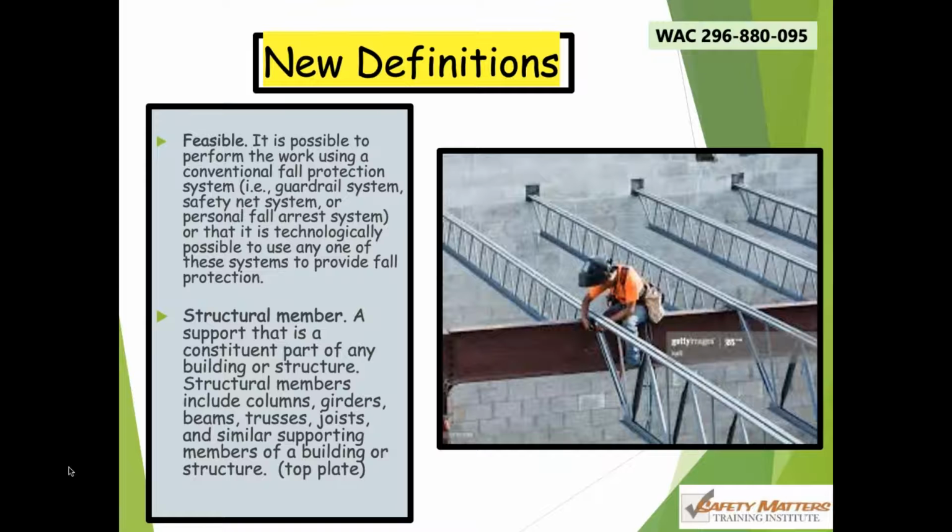So we're down to 2 trigger heights, you guys. We have 0 and 4 feet basically are the 2 trigger heights. OSHA has trigger heights of 0 and 6 feet, and so we wanted to be at least as effective as they are. In fall protection and construction, we already had the 4-foot rule. If you were on a working walking surface above 4 feet, you had to protect. So we've gone to a 0 and 4-foot rule. That's pretty much it, guys, 2 trigger heights. There's a few little exceptions here and there. Construction has a few little exceptions. Ski lifts have a few exceptions as well. But basically, it's going to be 0 and 4.